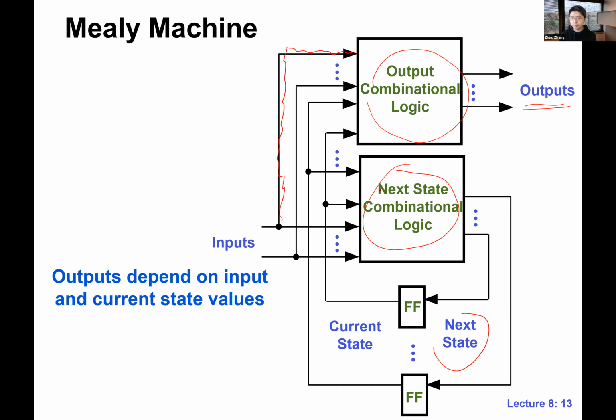So Laura, can you elaborate? Can you clarify what you mean by if you use? Yeah, I was going back to the example where you talked about an inferred latch. I noticed how it just used the equals sign and not the arrow. So I was wondering, if you replaced out equals D with out arrow D, would that still be an inferred latch? You're talking about the Verilog code?